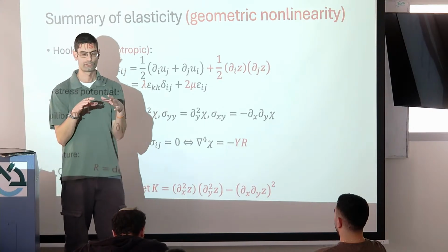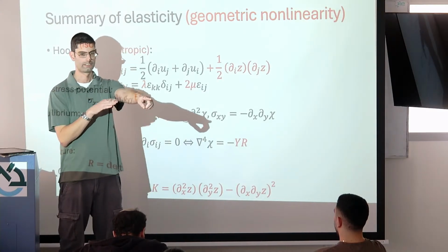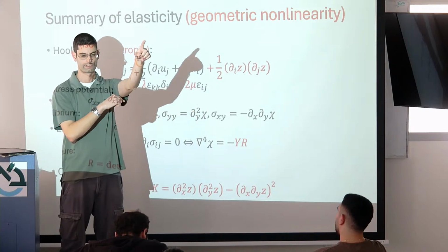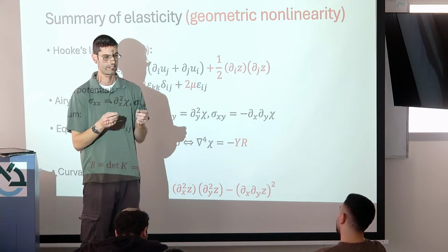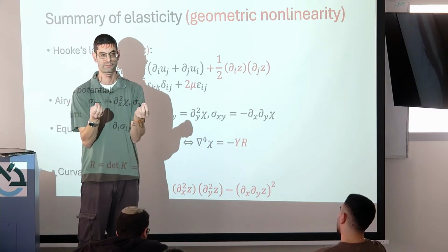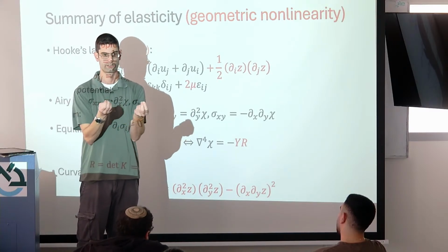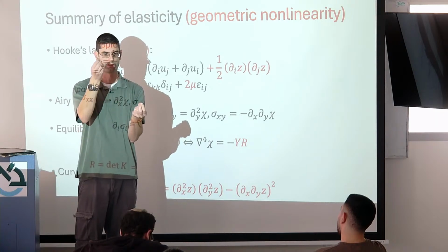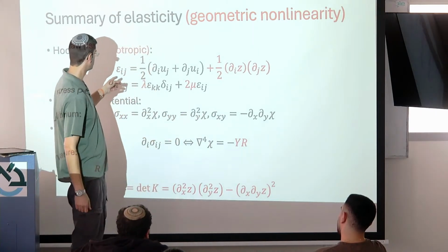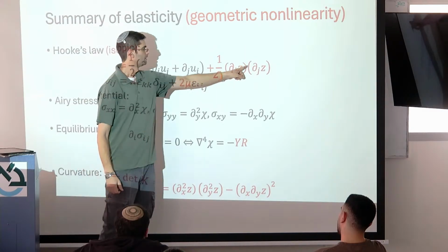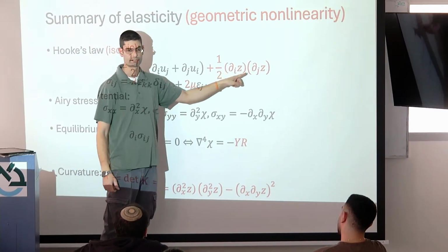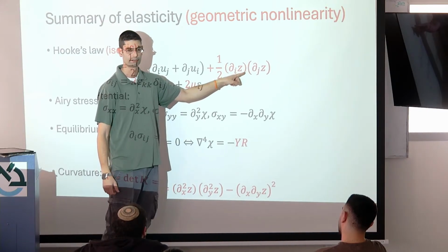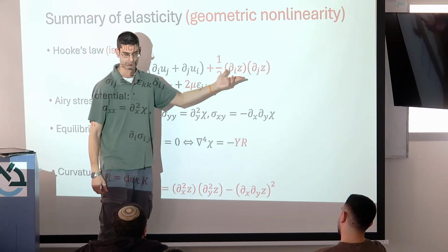we're effectively changing distances. So if we have distances in the plane, now we have distances out of the plane. This is like changing the metric of the system. It changes the relation between two different points in the plane. Their distance is no longer x, it's the square root of x squared plus z squared. And what this means is that the strain tensor gets this z squared behavior. This is just the Pythagoras equation, the Pythagorean theorem written in terms of derivatives.